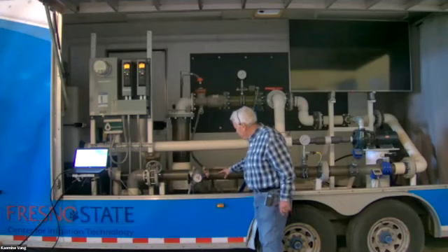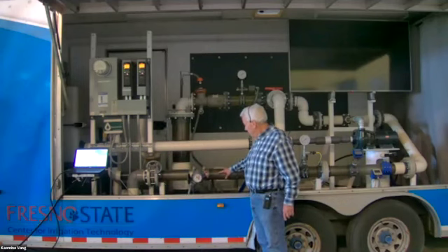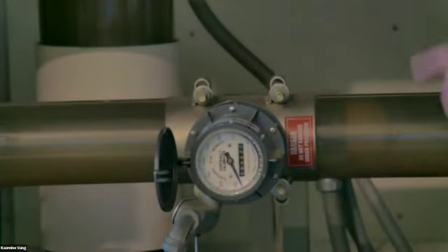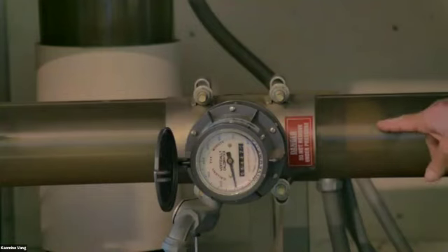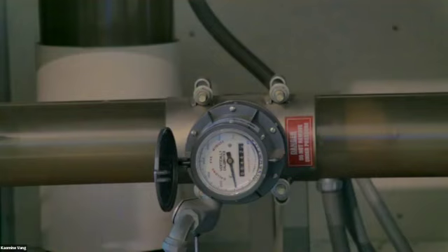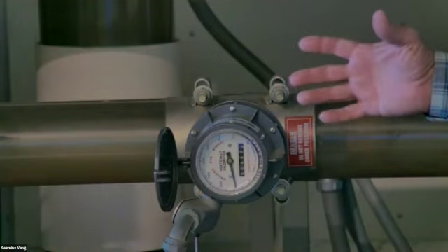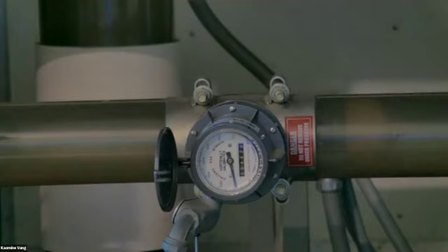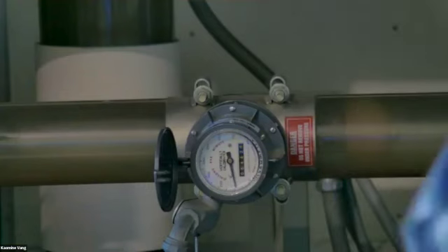So here's our flow meter here. It's not even turning yet, and you'll see it start to wind up. See, there it goes. Open it up a little bit. Okay, now it's turning fast. You can see it turning there faster. The flow meter's turning, but it was a soft start. So it took several seconds to go from 0 to 60 hertz in this case, because we're running full speed right now. That's what a soft start is. Let's do it one more time.